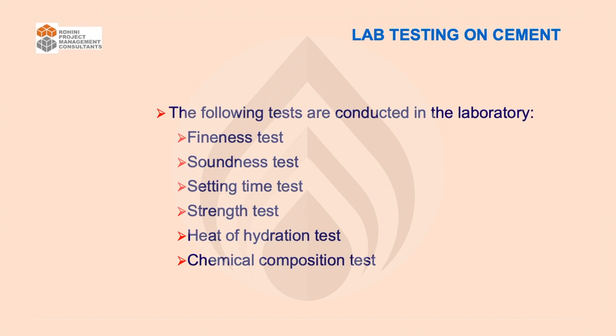So each cement has to be tested for all these parameters. You have fineness test, soundness test, setting time. Setting time is actually a very vital thing when we are working in hydraulic structures, right? Then you have strength.